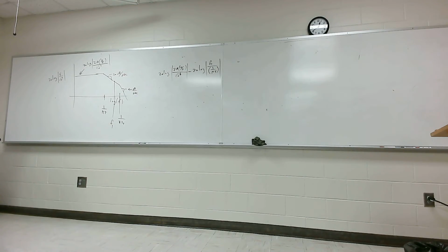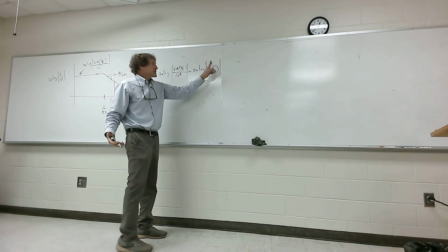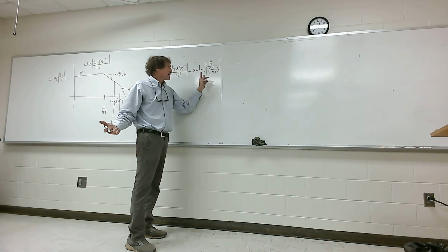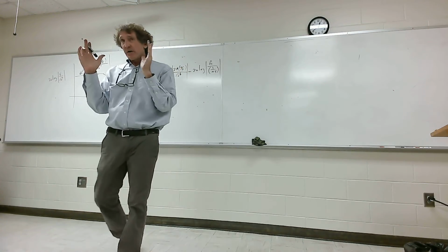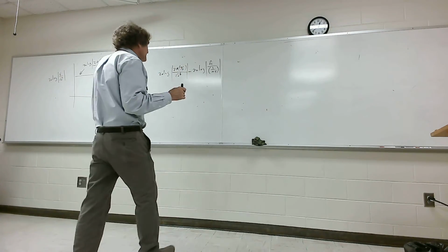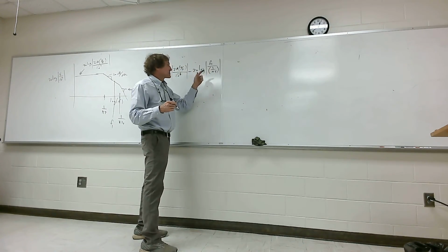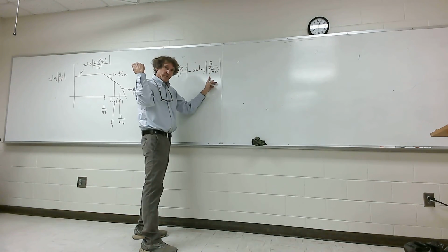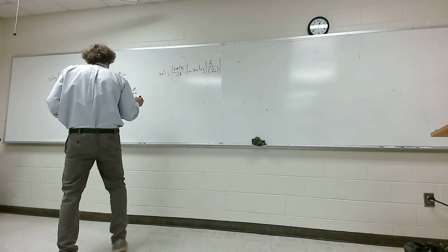Do y'all follow me on that? You pick a value of F, and that would give me the answer, because remember, it's 20 dB per decade. If this is 10 times this, 20 times the log of 10 is 20, so you'd be down 20 dB. But if you don't go a full decade, then you have to adjust and say minus 20 times the log of the frequency you stopped at, divided by the frequency where the break was.